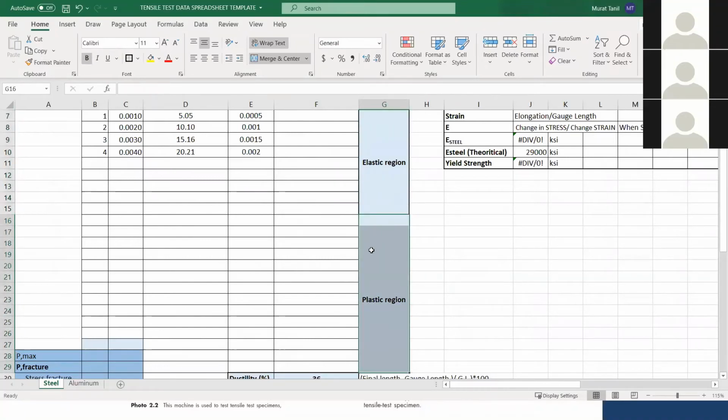Because you don't want to deform your member in your design permanently. You can allow your member to deform elastically because you know that when the load is removed, you're okay. Let's look at the case of a bridge. If you're driving from West Bank to the city, that bridge is shaking all the time. Sometimes we have 18-wheelers, sometimes small trucks or large trucks, etc. But the bridge is deforming every time it sustains a high amount of load.